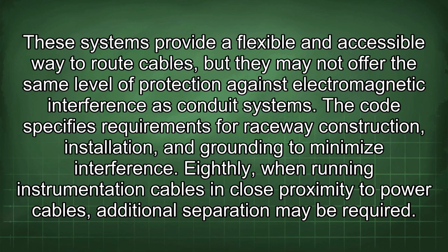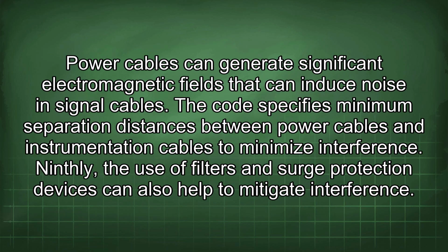Eighthly, when running instrumentation cables in close proximity to power cables, additional separation may be required. Power cables can generate significant electromagnetic fields that can induce noise in signal cables. The code specifies minimum separation distances between power cables and instrumentation cables to minimize interference.